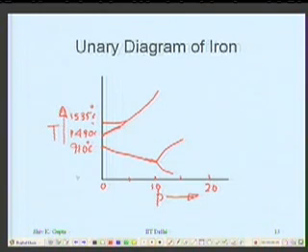Here we have, starting from the absolute 0, around 1 atmosphere, the BCC form of iron, what we call alpha. Then from 910 degrees centigrade, where the transformation occurs, it becomes FCC iron, which we call gamma iron. It remains up to 1490 degrees centigrade or so.